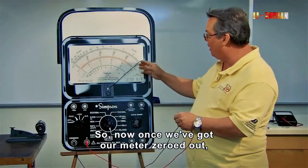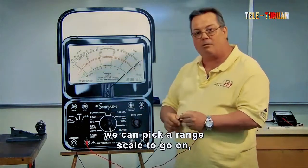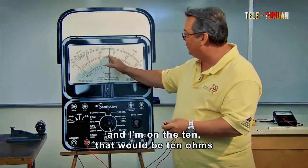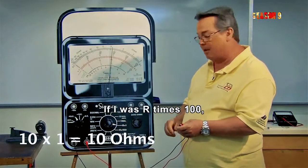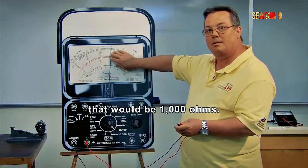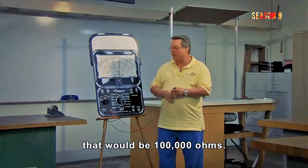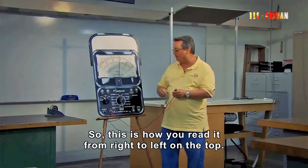So now once we've got our meter zeroed out, we can pick a range scale to go on depending on what we think that ohmic value is. We have R times 1. So if I came up to here and I'm on the 10, that would be 10 ohms when I'm on R times 1. If I was R times 100, that would be 1,000 ohms. And if I was R times 10,000, that would be 100,000 ohms. So this is how you read it from right to left on the top.